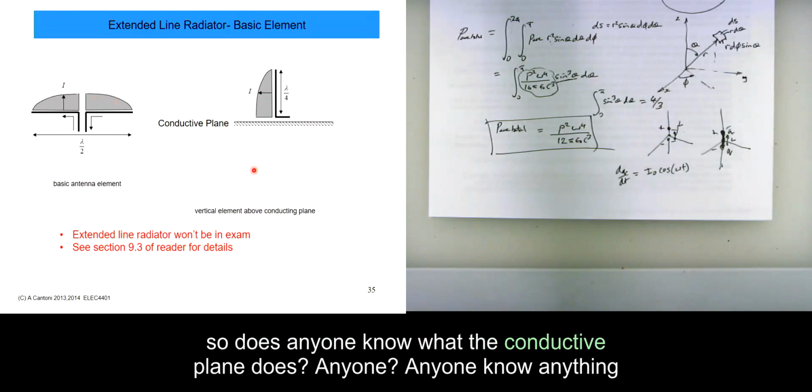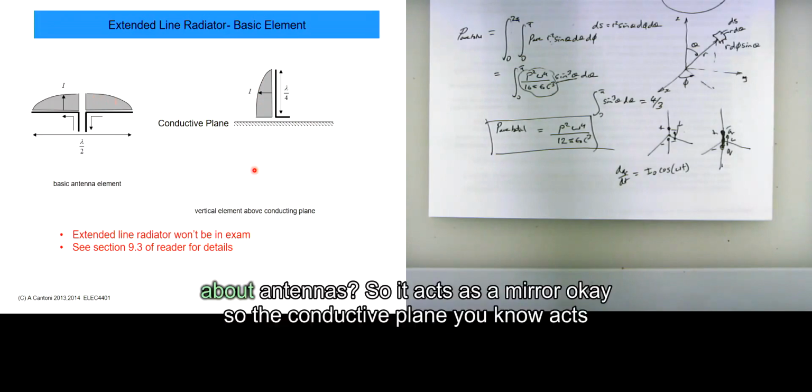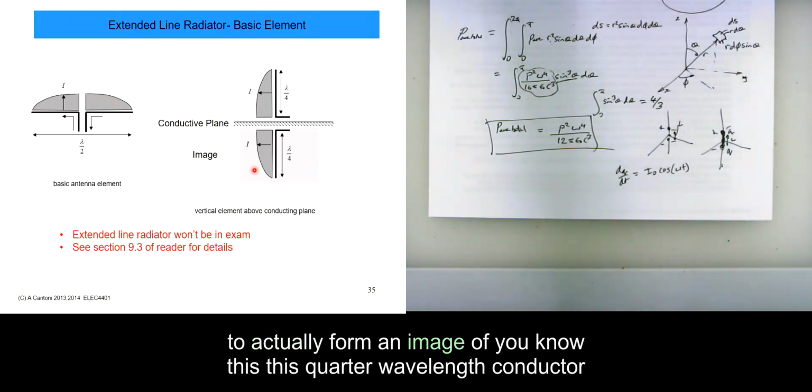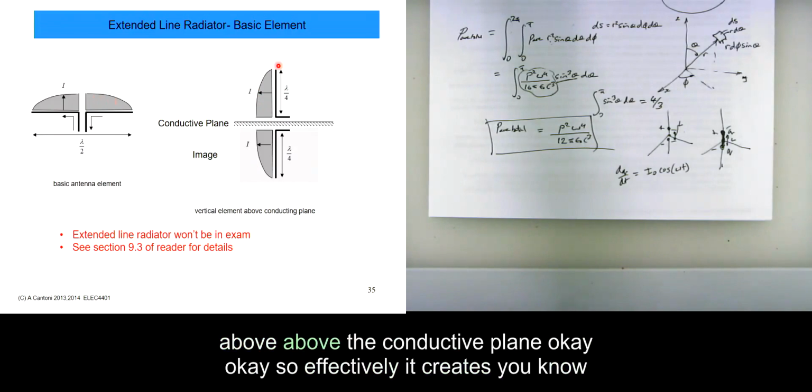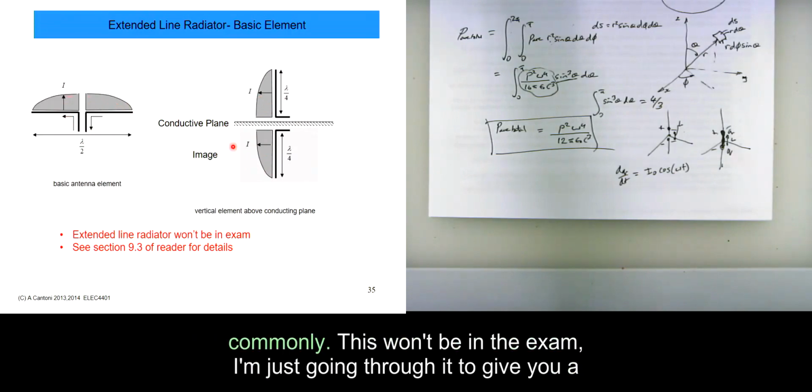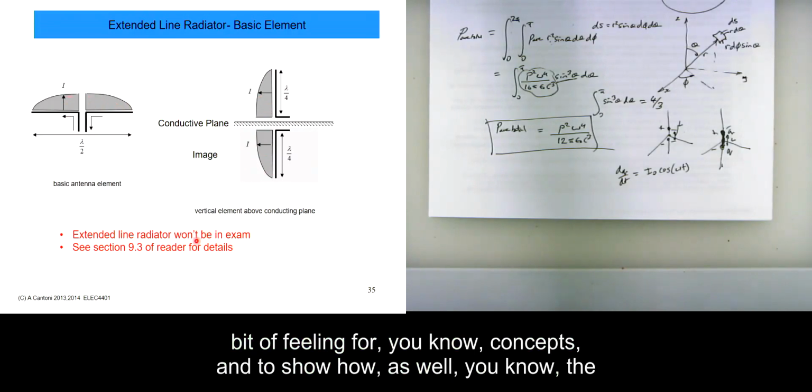Does anyone know what the conductive plane does? Anyone know anything about antennas? It acts as a mirror. The conductive plane forms an image of this quarter wavelength conductor below the plane, so effectively it creates again one of these half wavelength antennas. So those are the two that you see very commonly. This won't be in the exam. I'm just going through it to give you a feeling for the concepts.